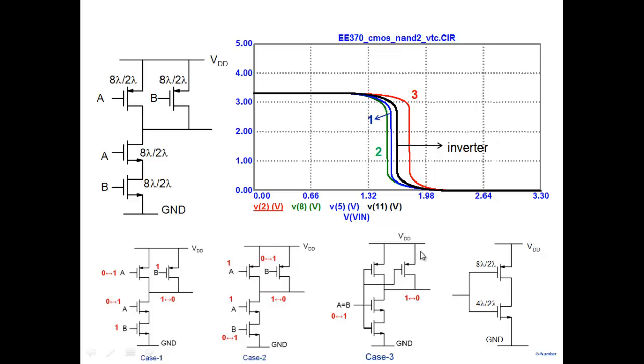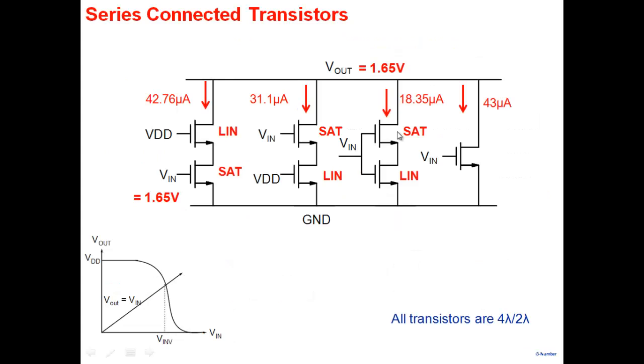What I'll do is use the expression that we had for an inverter, approximately the same here, except that the size of the PMOS will no longer be 8 by 2. We will make it 16 by 2. And these two NMOS connected in series are equivalent to a transistor of similar size. Note that the currents, if I double it, will be close to this.